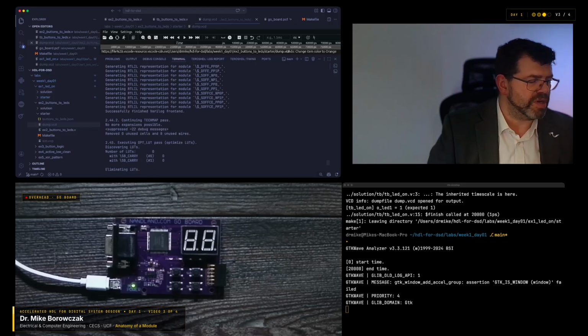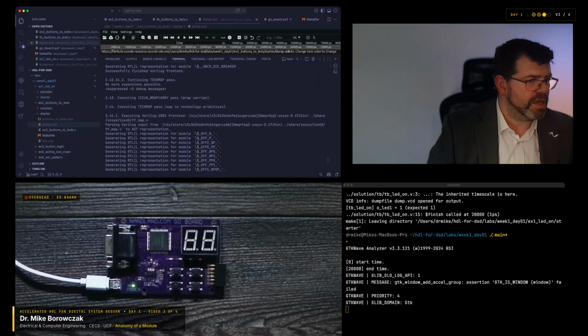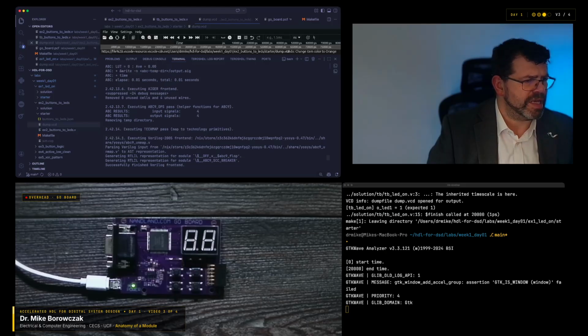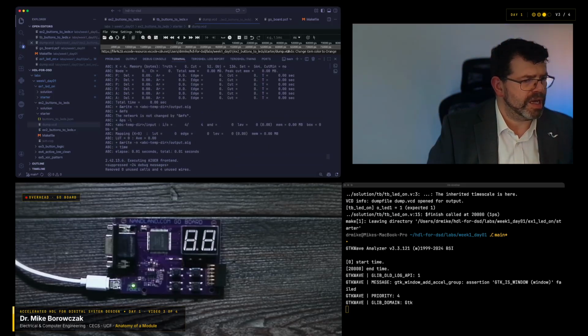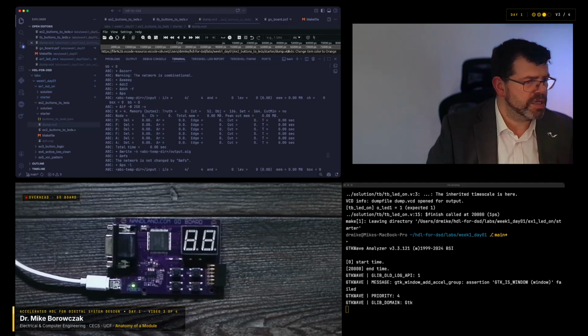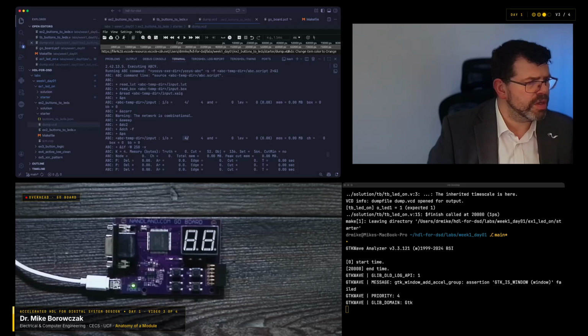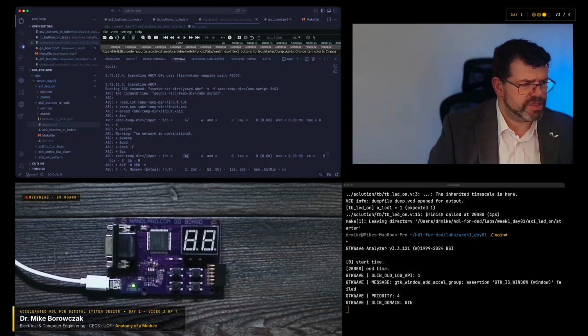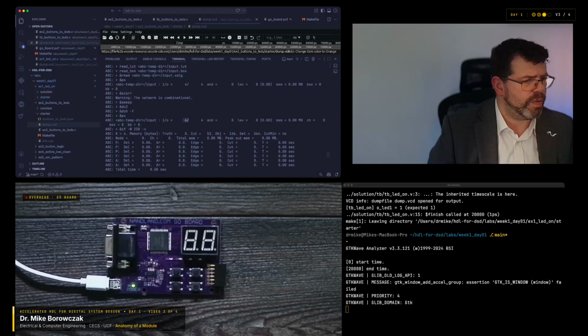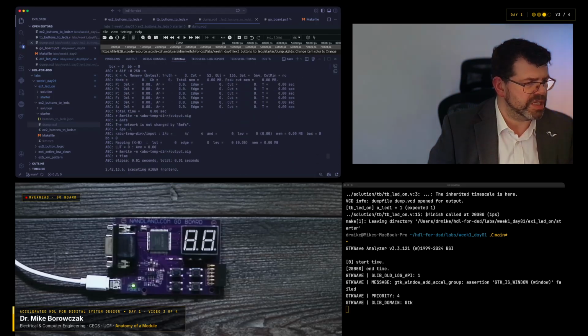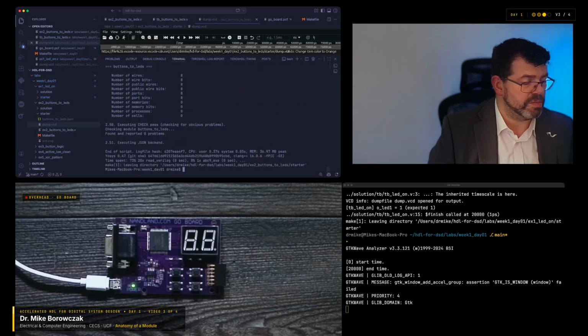Now, what's interesting here is we're not doing any logic, right? We aren't really mapping anything. And so how many actual LUTs we use is going to be interesting here because the network is combinational. We see our inputs and outputs here, 4, and it didn't take very much time. And that's actually about it. So really not much going on here except direct wiring. So not surprising that we don't see any LUTs right here. No LUTs needed. This is a direct wiring from inputs to outputs with no logic in between.